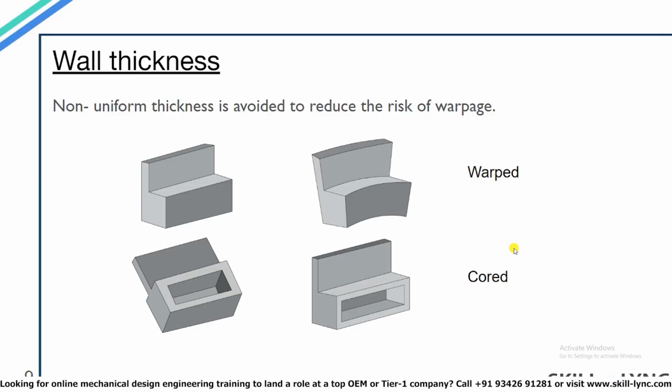Usually the thickness values used for plastic components vary from 0.6 mm to 5 mm. If we try to make parts thinner than 0.6 mm, then there won't be a proper filling of material in the mold. The material itself will solidify before reaching the ends. This defect also has a name. It is called the short, which will be covered in the defect section. For thickness values higher than 5 mm, gas-assisted injection molding is used.